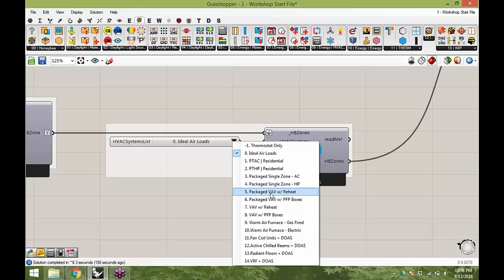But the most important thing to remember is that for systems 1 through 10, when they deliver hot or cold air, they deliver it with just a single system. They're trying to both heat and cool the space with hot and cold air and deliver the minimum amount of ventilation to make sure that the occupants don't suffocate or get funky smells in their building.